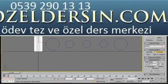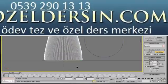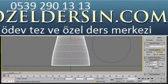There we are, we've just finished creating our spout. We'll go back over to Path Parameters, and we're going to type in 99, press Get Shape, and click on the large N-gon. Notice the shape now. There's just one more to do. We'll go back over to the path and type in 100, press Get Shape, and we're going to select the N-gon that's on the right hand side. That's just given us a bit of a bevel underneath.